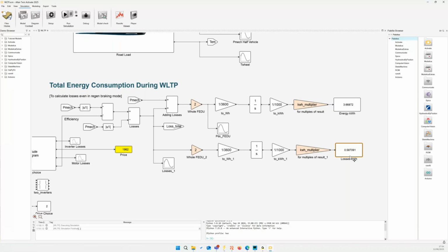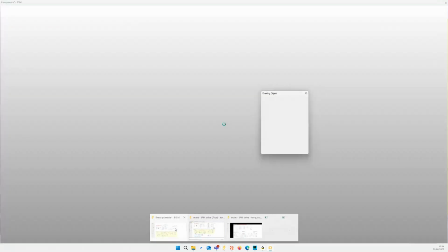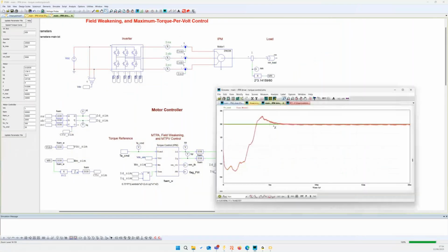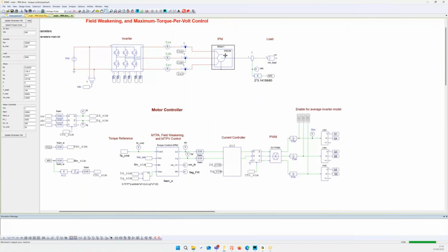So the process, if I want to summarize, is you start inside PSIM. You decide what is the fidelity you want. You have several options. You can have a drive that runs in 1 second. Here it is. This is the drive. But everything here is ideal. You can have an FEA-based, or rather an FEA-exporting model coming from Flux. By the way, if you are not using Flux, we also offer a model that enables you to change the LD and LQ values dynamically. This will capture saturation effects, but the Flux model also captures other effects such as spatial harmonics.